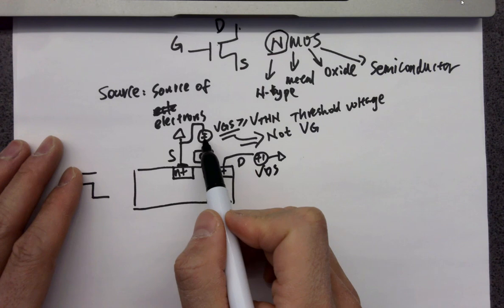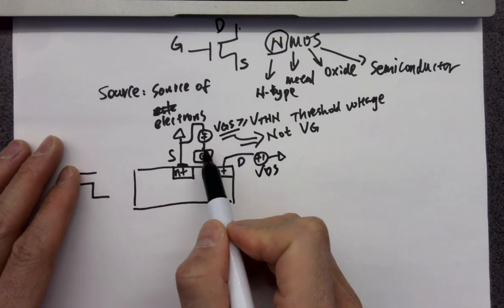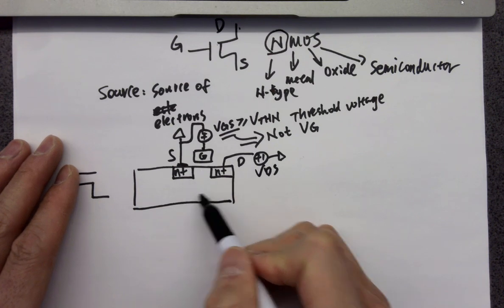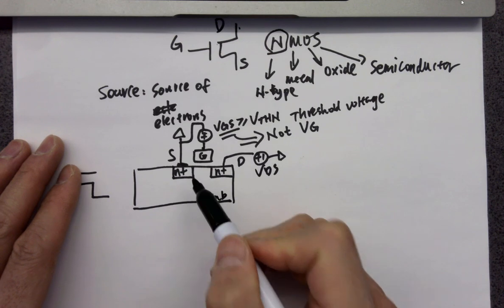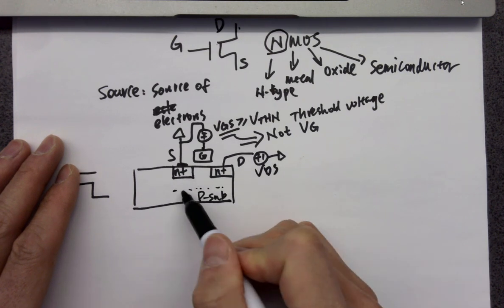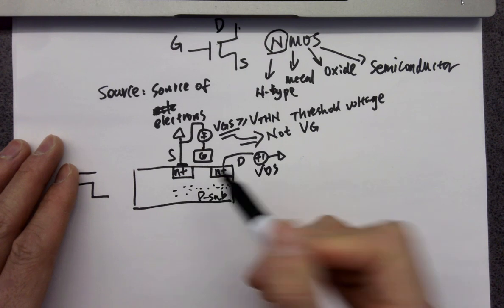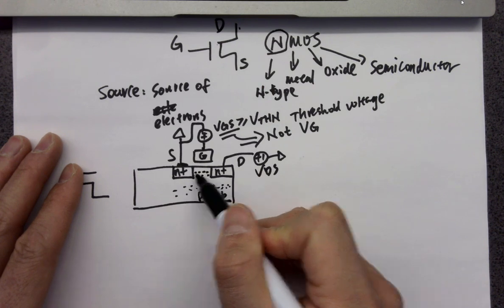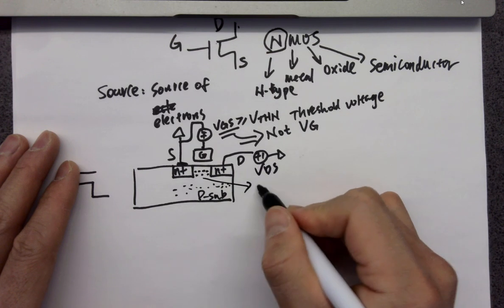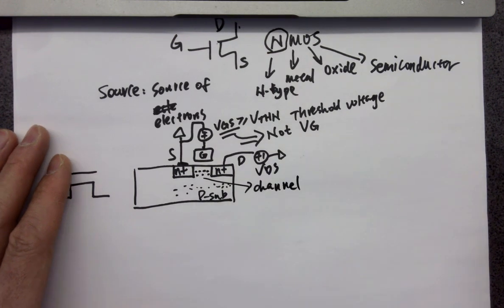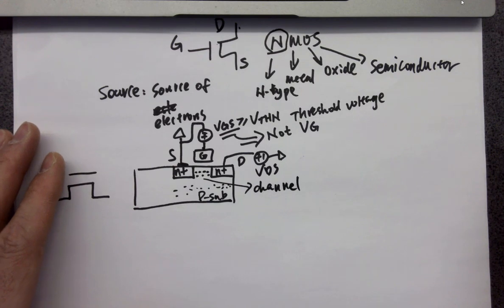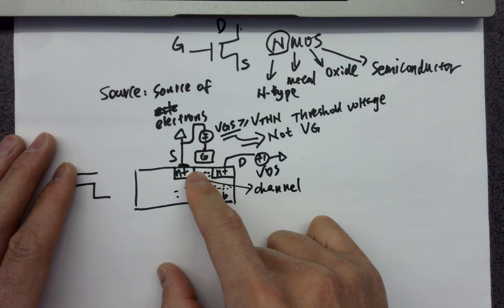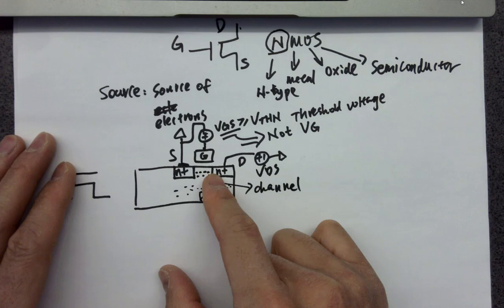So the way that works is because you are applying a positive voltage across VGS, it's creating an electric field which attracts electrons in the P substrate. Electrons are free electrons, even though there are not too many. It's a P type, right? But there are still free electrons. So free electrons will be attracted underneath the gate to form a channel. It's called a channel, the electron channel, right? But it's static, nothing's moving. If you only provide a VGS but not VDS, there will be only an electron channel being formed underneath the gate, but nothing is moving, all right?